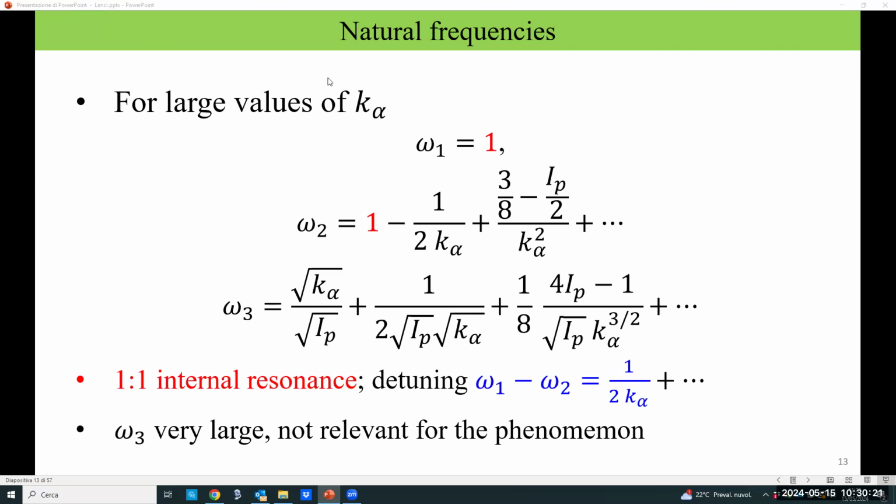centrifugal forces. So what I'm asking is, apart from just having sine omega t, do we need to add another sine of capital omega to represent the rotation of the turbine blades, and the small omega as a function of amplitude representing the nonlinearities, and then do the analysis? Then these terms will probably change, and the zone of resonance and instabilities will change? Or do you think your larger terms will still dominate?